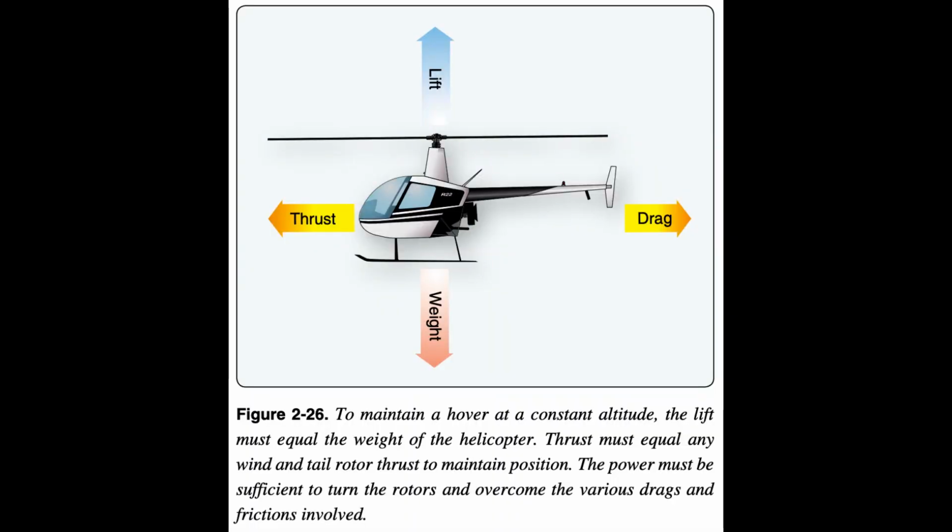Hovering flight. Hovering is the most challenging part of flying a helicopter. This is because a helicopter generates its own gusty air while in a hover, which acts against the fuselage and flight control surfaces. The end result is constant control inputs and corrections by the pilot to keep the helicopter where it is required to be.